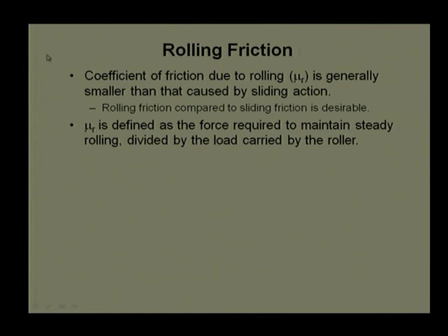It can be defined as a ratio of forces, and also as a ratio of moments. In this case, we are assuming a ratio of forces: the force required to maintain steady rolling divided by the load which is applied on the roller or tribo pair.